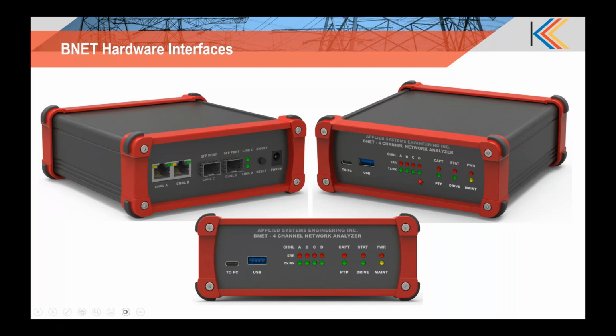And then also you'll see the capture LED there, the PTP indication when you have an active connection to your time source, and then a general status LED and drive presence indicator. And then your other standard LEDs are power, and a maintenance LED that indicates that the BNET accessory is detecting connection to your 61850 test set application, which is incredibly beneficial during test time.